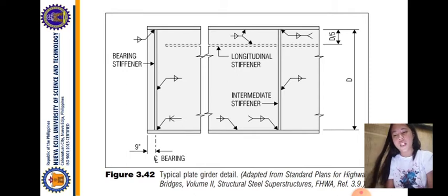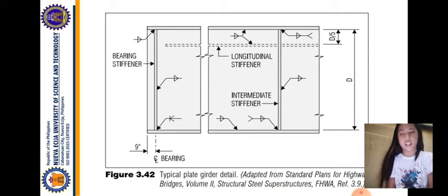Longitudinal stiffeners are not required to be continuous and may be cut at intersections with transverse intermediate stiffeners. In AASHTO LRFD 6.10.11.3, the designer should determine the stiffener location so that both service limit state and strength limit state requirements are satisfied.